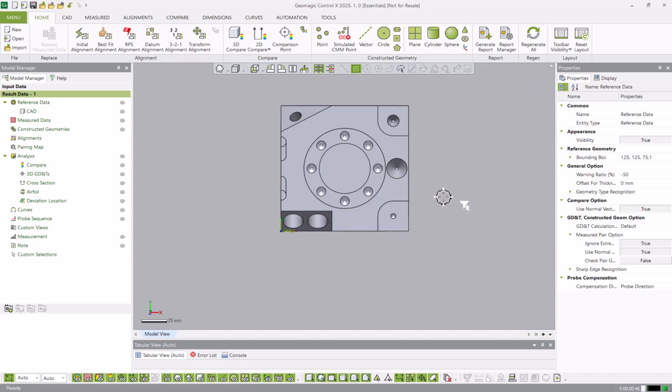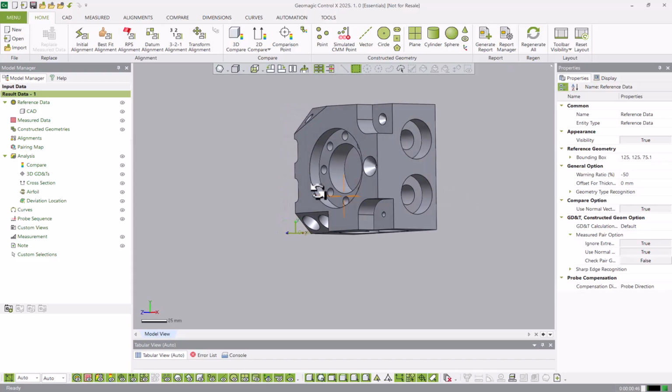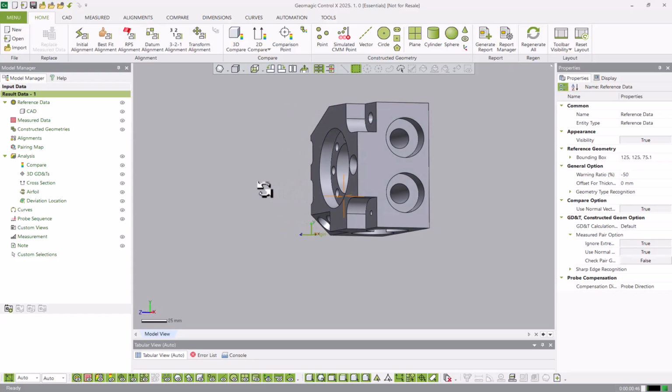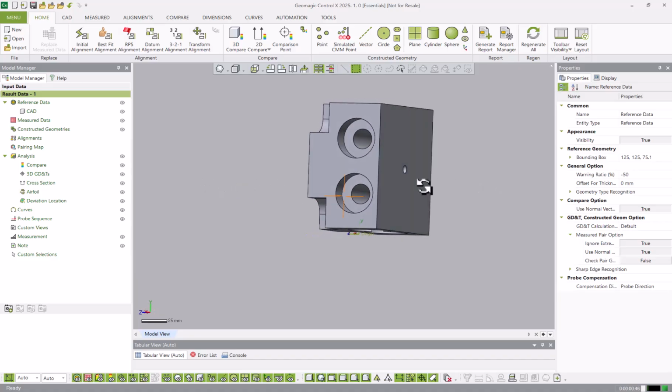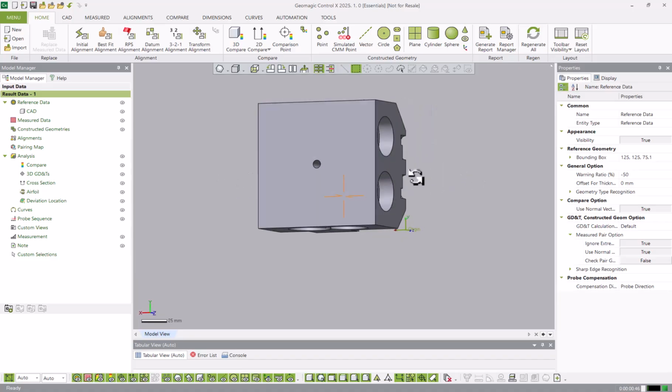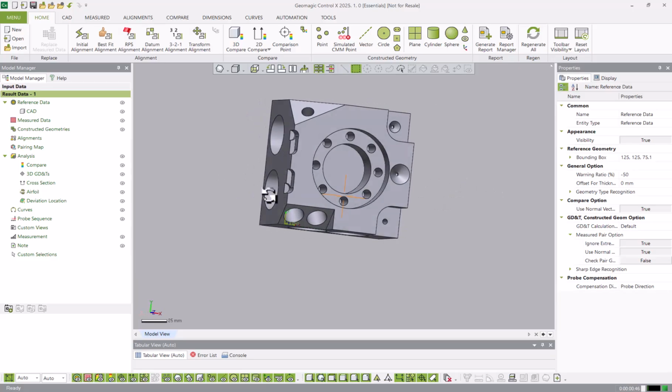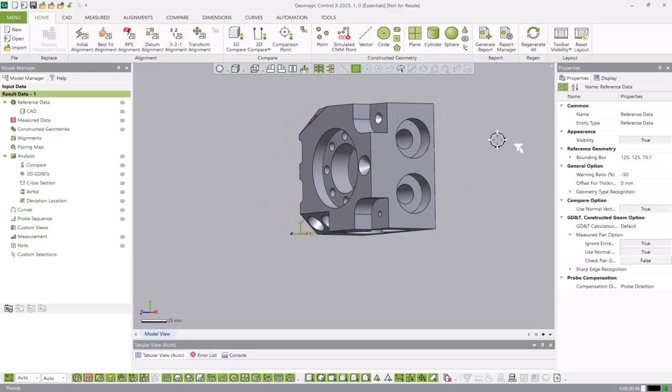And following the zooming in and out, in order to rotate the model, you can click and hold the right mouse button, and whilst you have the mouse held, you can move your mouse. A rotation icon would also be placed on the screen. This is how you can rotate a particular body about its view.